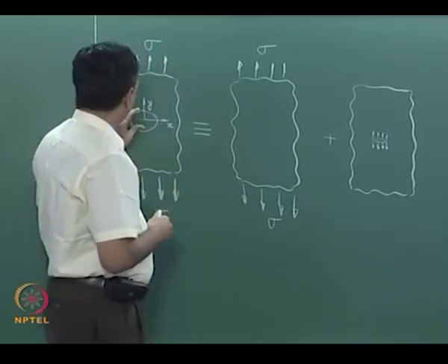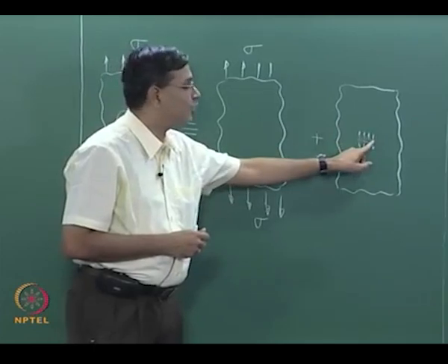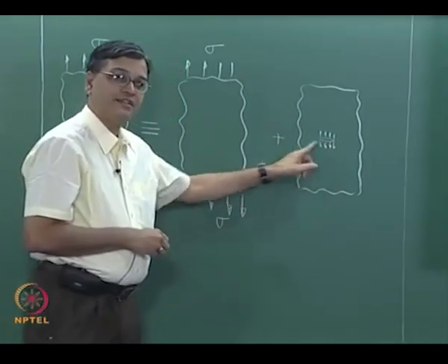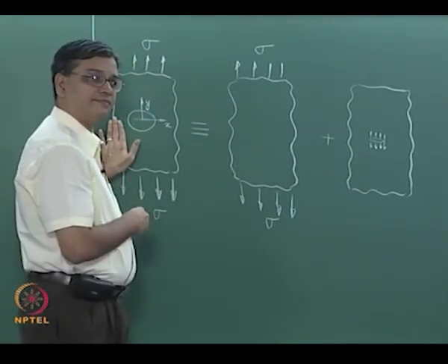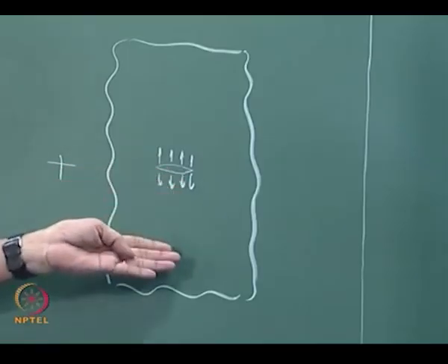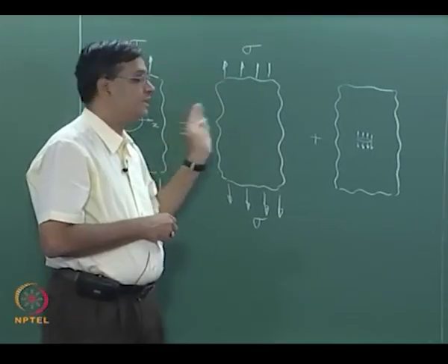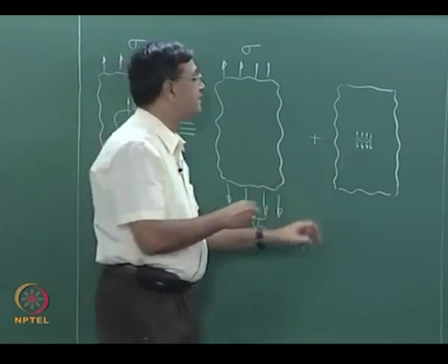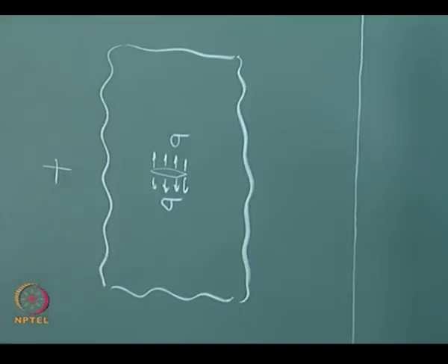So, if I maintain the crack is opened up by a suitable force system, that would automatically specify what is the singularity in this crack tip, it will model the crack behavior, and when you add these two problems, this problem is possible. And from such consideration that stress intensity factor is same for this problem and the final problem, this force or the load is nothing but sigma.